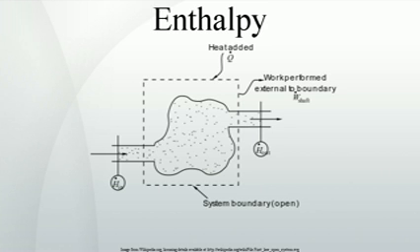Relationship to heat. In order to discuss the relation between the enthalpy increase and heat supply, we return to the first law for closed systems, dU equals δQ minus δW. We apply it to the special case that the pressure at the surface is uniform. In this case the work term can be split in two contributions, the so-called PdV work, given by PdV, where here P is the pressure at the surface, dV is the increase of the volume of the system, and other types of work δW' such as by a shaft or by electromagnetic interaction. So we write δW equals PdV plus δW'.